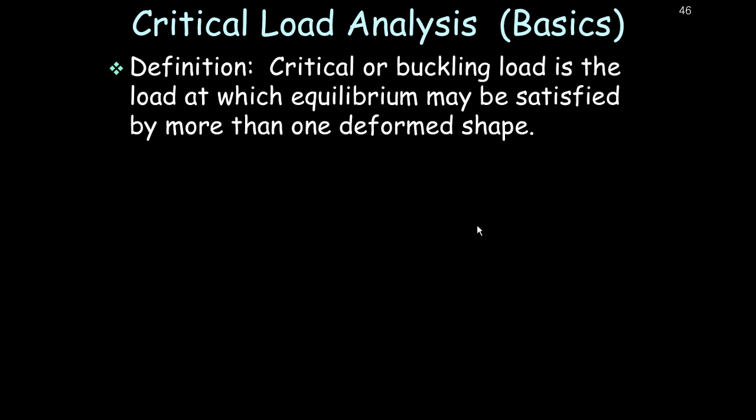In your second order analysis, what you are doing is either iteratively or in increments, applying more and more load on the structure until you reach equilibrium under the given loads. A critical load analysis is going to take your given loads and figure out what scale factor against those given loads would make the structure, let's say, elastically buckle. So what you're going to get back is a load factor of how many times your current load could be put on there before the system would buckle. You'll get a nice view of those buckled shapes, but you don't really have any history on how you got there. And that's the nice thing about the incremental analysis: you can see the structure becoming unstable, when it became unstable, and how it got there.